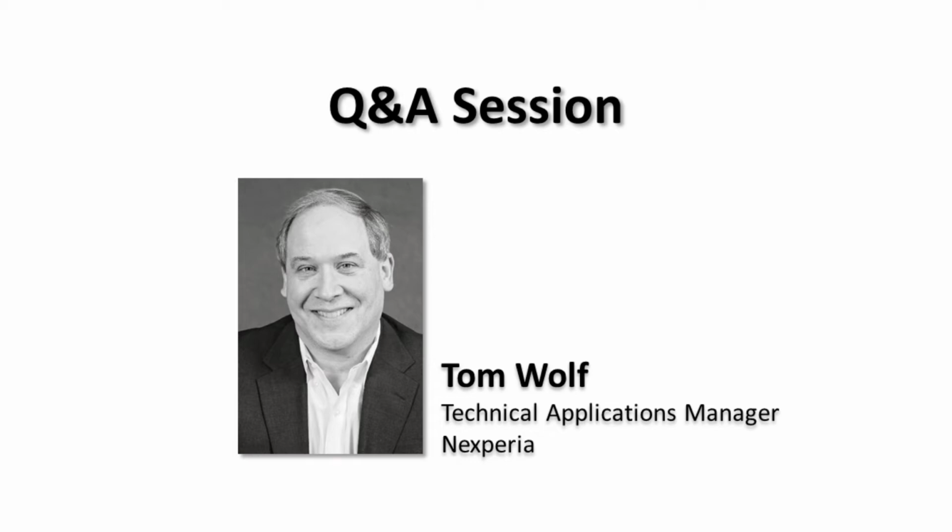Is there a top-side or dual-sided cool version of the LFPAK available? Not at this time. I mentioned it during the presentation itself, that our part essentially is double-side cooled already. It's got a drain copper pad on the bottom of the package. It's got a source copper pad on the top, which then routes back down again. So there's no bare metal plate on the top where you would connect a heat sink.